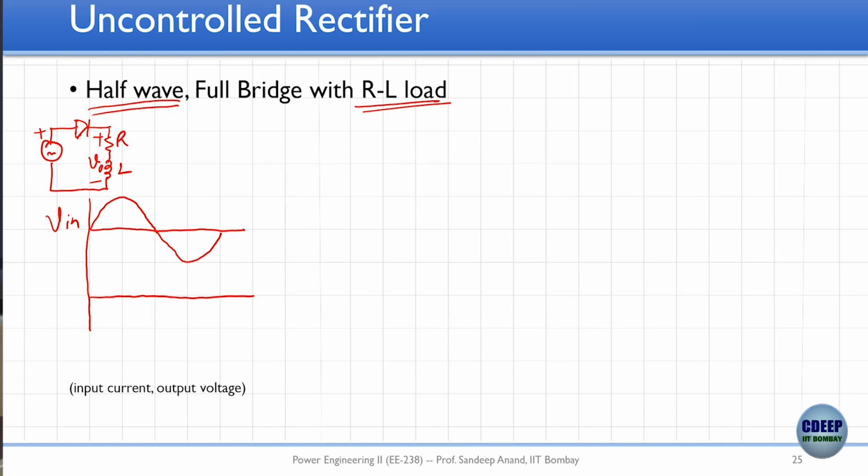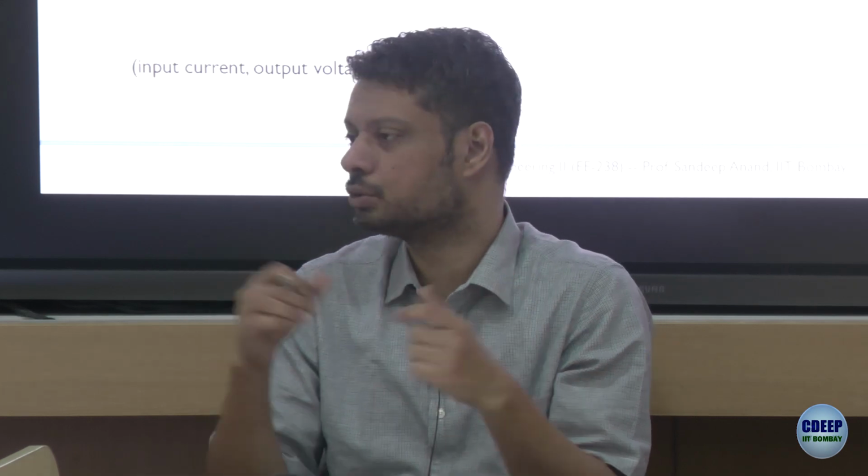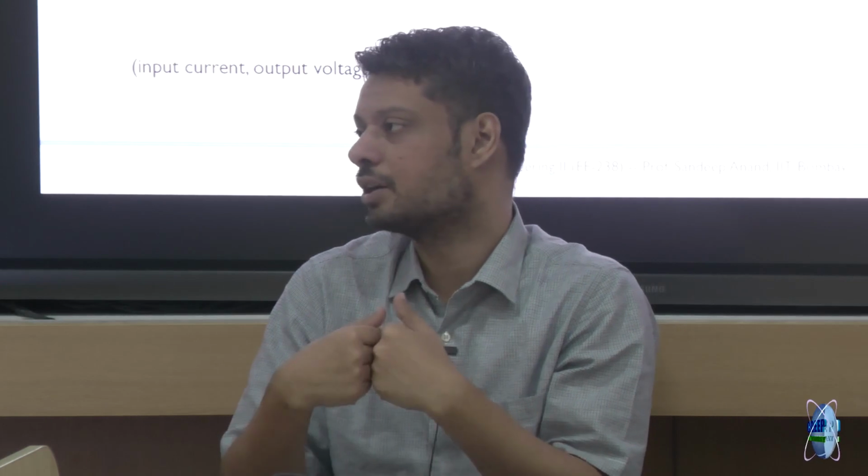So my output voltage I am referring to is the combination of R and L, right? So think of R and L as your load. You have seen the rheostats in the machines lab last semester. Those rheostats are variable resistance, but they are wound in a coil kind of fashion, and therefore of course they would also have inductance. So just imagine a practical rheostat is connected across the output terminal, and you are measuring the voltage across the rheostat. In fact, you can do this experiment in the lab also, right?